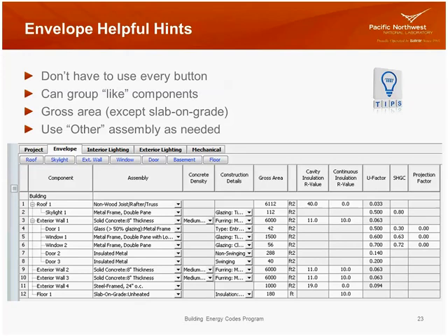If they have different values, you've got to separate those out. The other thing about the square footages involved here is there is one exception to doing your takeoffs, and that is slab on grade. It's very important. And you see the screenshot here where it's showing you the column right after construction details. It shows gross area, which is where you would enter your takeoffs for each assembly.